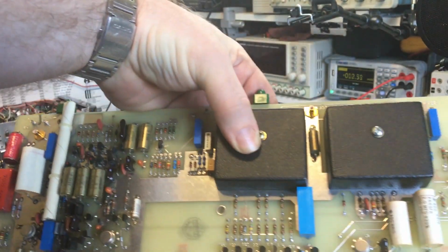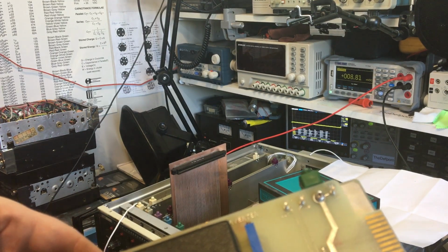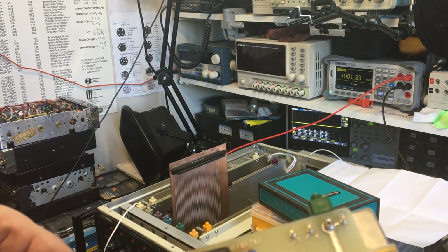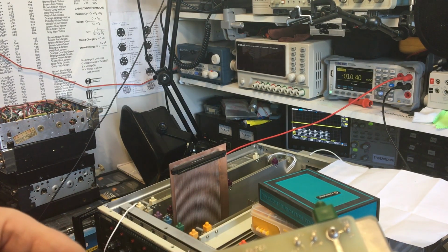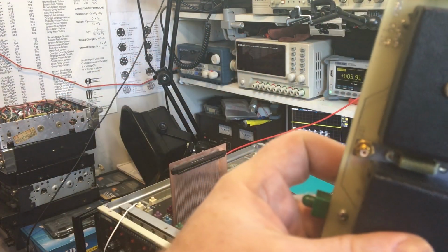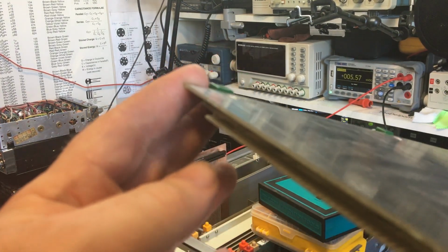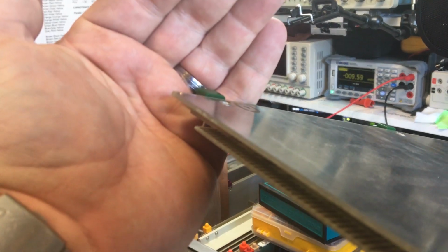Okay, so what I've done here is I've pulled out the AC/DC board and I'm checking the actual physical connections on the board. So I'm looking for pins 57 and 58, so that's 54 there. So it's 56, 58, no connection. And if I look on the back of the board, which you probably can't see, if it would focus it might help a little bit, but you probably can't see in there. There's no connection on the back of the board either.